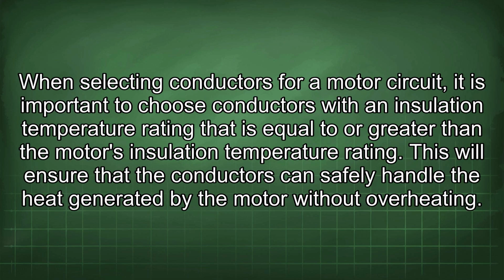When selecting conductors for a motor circuit, it is important to choose conductors with an insulation temperature rating that is equal to or greater than the motor's insulation temperature rating. This will ensure that the conductors can safely handle the heat generated by the motor without overheating.